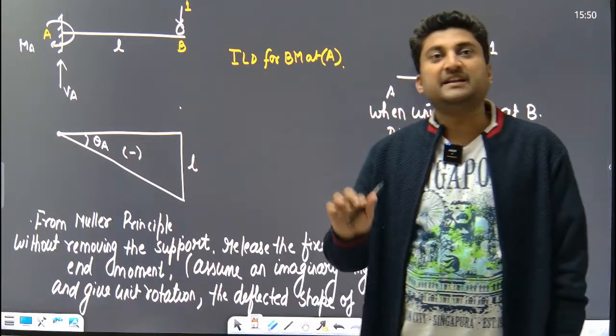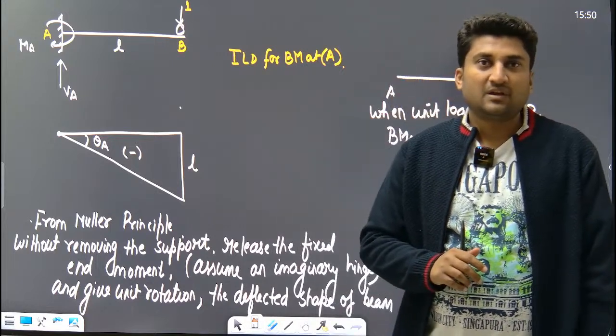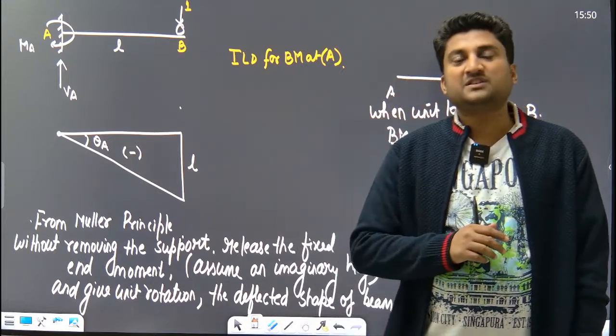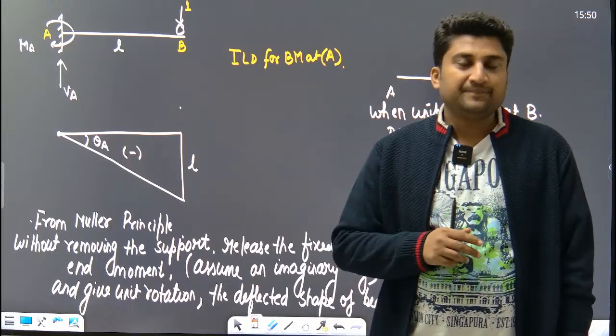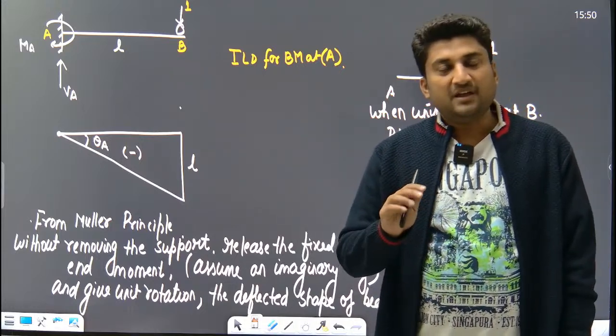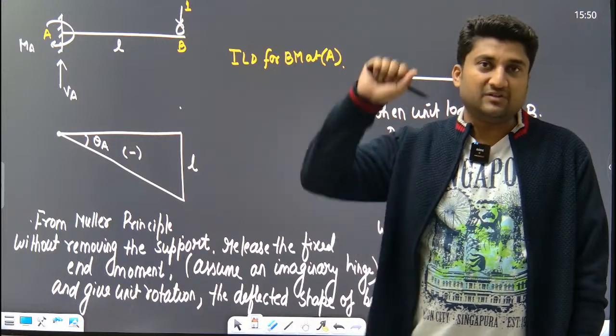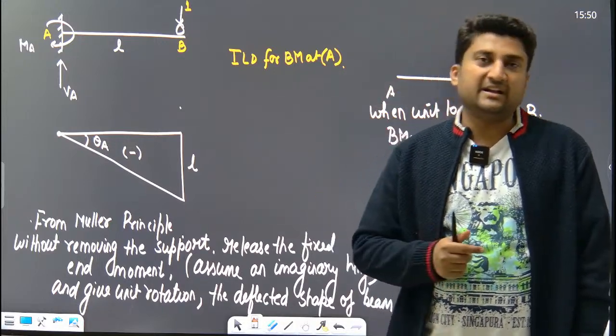What is the ILD for shear force? Without removing the support, cut the beam at the RHS of A, and without removing the fixed end moment, give the unit displacement. The deflected shape is ILD for shear force.